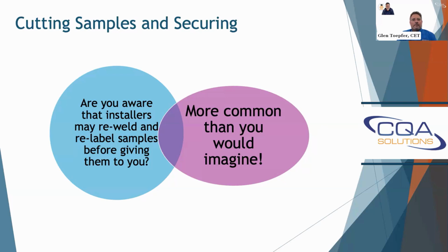And you think about it, your samples in any other industry, you sample groundwater, sample soil, contaminated soil. You get your samples, you fill out a chain of custody, they stay in your possession, you sign off on them for the person in the next possession that gets them, and until the samples get to the lab and are sampled, that chain of custody form accompanies them. But in the geosynthetics industry, we cut them out and leave them with the installer for nights, days, and you get them back. Are you sure they're your sample or not?